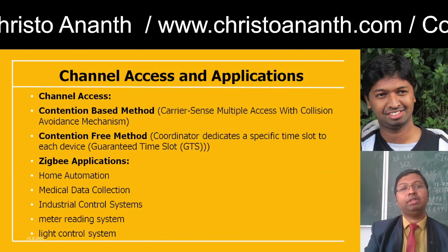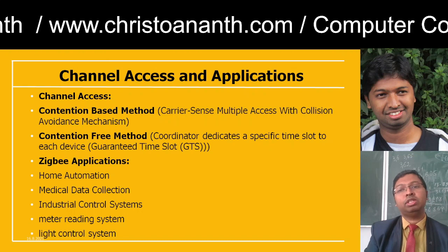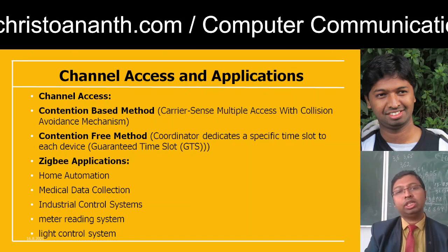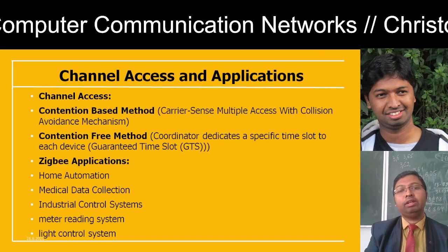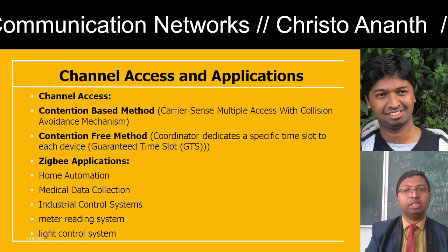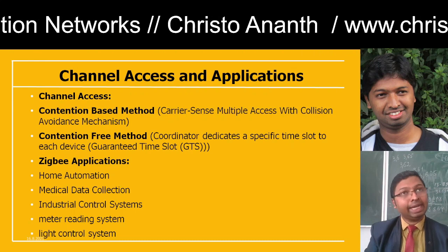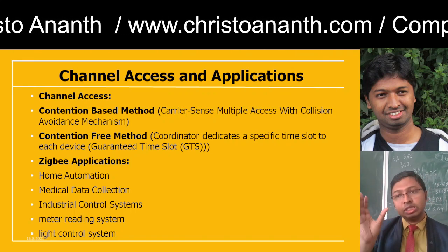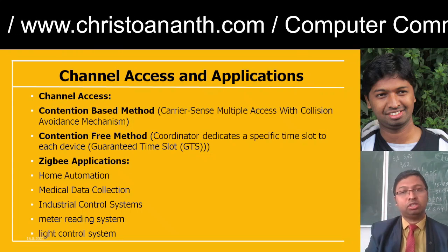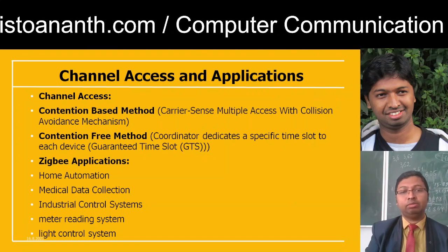And here we have channel access. Here you will use CSMA-CA, carrier sense multiple access with collision avoidance. And we also have a contention free method, which is the guaranteed time slot, which means that the coordinator dedicates a specific time slot to each of the devices.